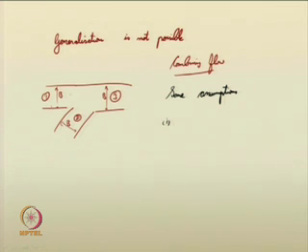We also assume that channel 1 and channel 3 are in the same line. This is also one assumption. We are neglecting the wall frictions, then depths in channel 1 and channel 2 are equal immediately above the junction. Say if this is the junction, around the portion above the junction, depth of flow of this channel as well as channel 1 are both the same.